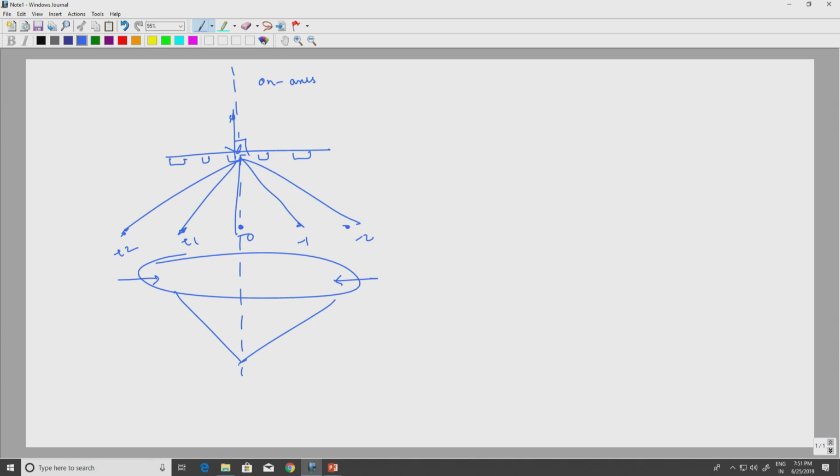Whatever falls within the numerical aperture, you will collect and then image. Now if I get a situation where the dimensions are reducing, that means I have a very small pitch. When you are illuminating this sort of small pitch, you will have your zeroth order, but your first order itself is going to be outside.